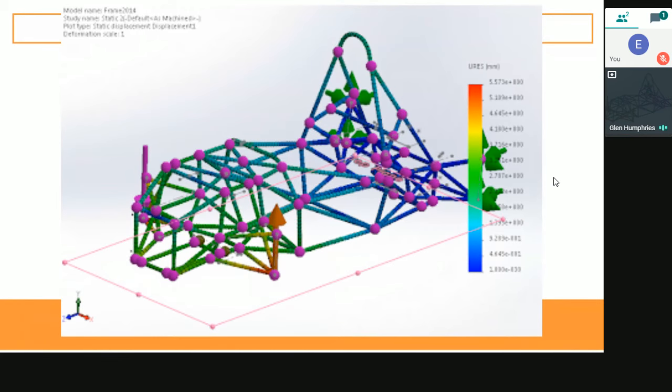members have been modelled, and that's because the pattern of loading from the wheels to the chassis obviously goes through the suspension, and in a very complex way, in a way where it's much easier to simply model the suspension and include that in the analysis than it is to try and do that realistically using individual forces. It's almost impossible to go through and work all that out and apply it directly to the chassis. So instead we use more components in our analysis to add in and provide a more realistic loading scenario.